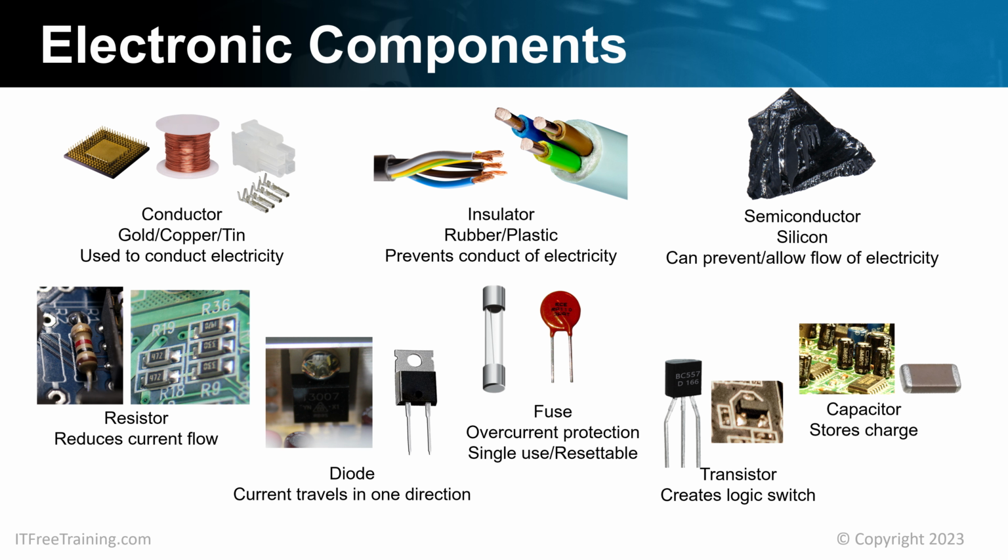Other things to consider are if you put the computer under a lot of load and the computer restarts, this may be a problem with the power supply, capacitors, or other components that regulate power. These problems may also occur due to heating problems, but it generally takes a little bit of time for the component to heat up before problems arise. If the problem happens within a few seconds, it is more likely to be a power problem.